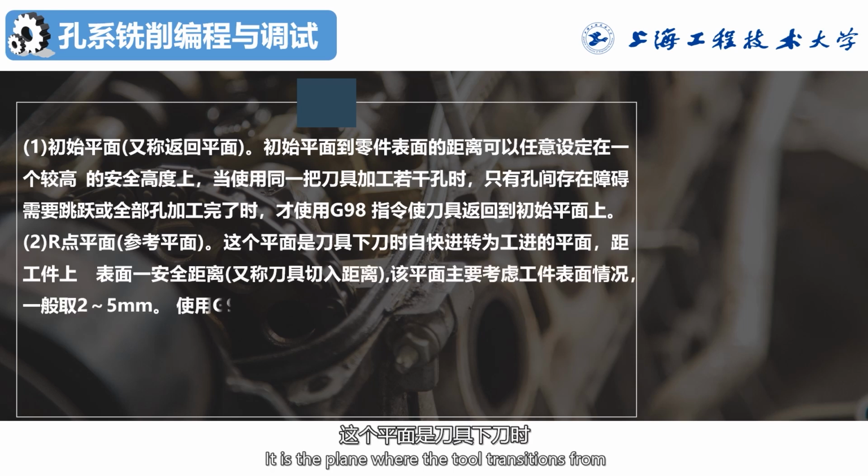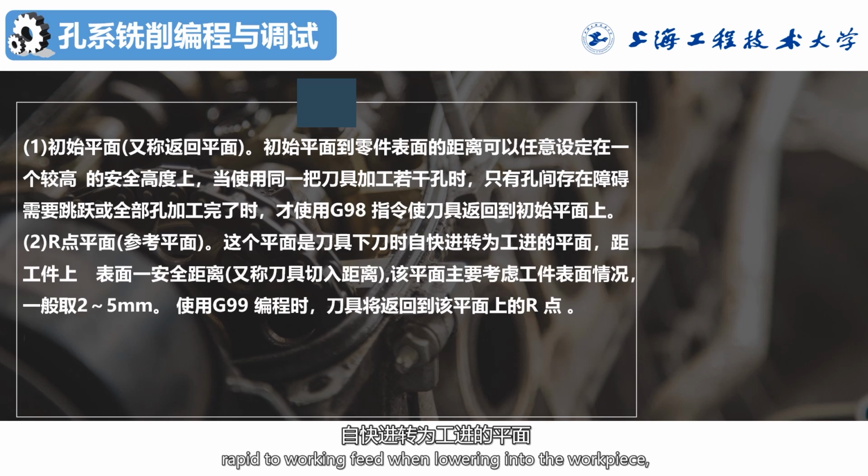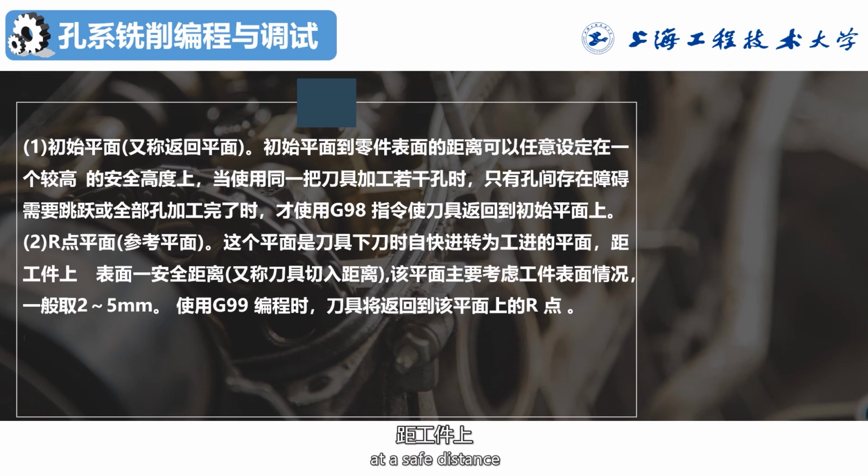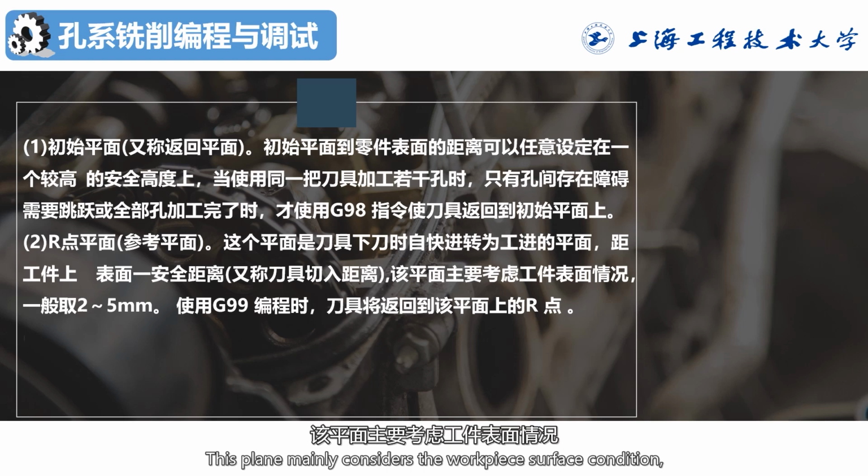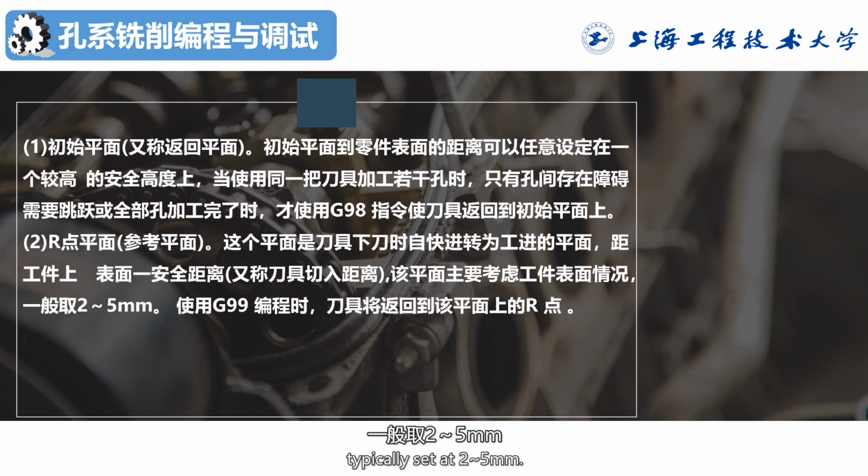It is a plane where the tool transitions from rapid to working feed when lowering into the workpiece at a safe distance, also called the tool entry distance. From the workpiece surface, the plane mainly considers the workpiece surface condition, typically set at 2 to 5 mm.